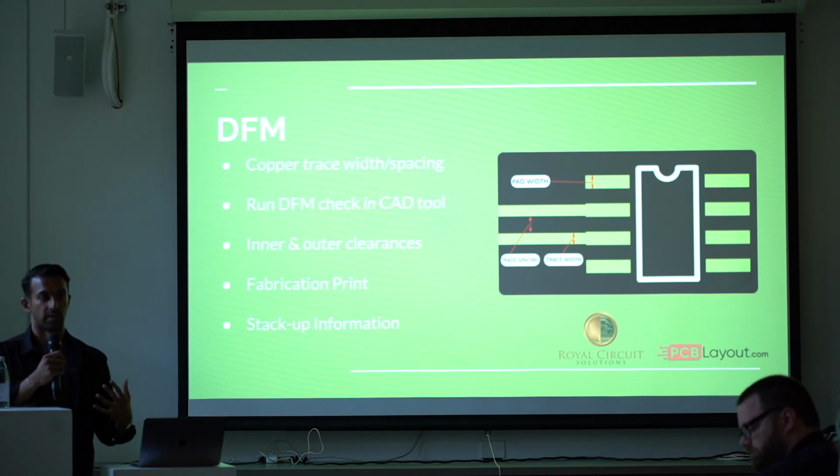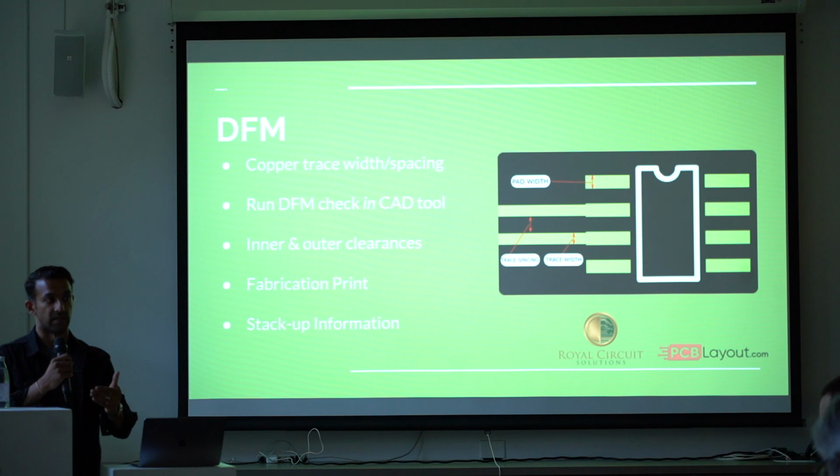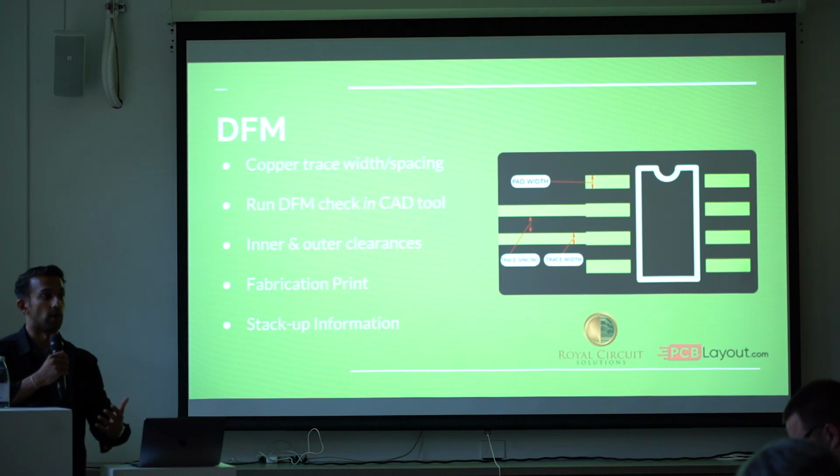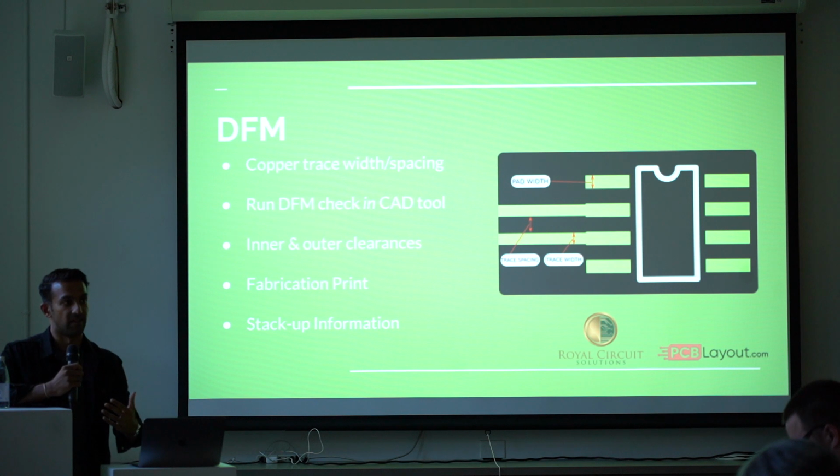So if you're running a particular design and you need a 50 ohm trace, for example, it's generally in your best interest to send us your requirements, and we would come up with a very specific stack up that would work for you and arguably be cheaper than what you can do or know on your own, because we know which materials to pick, how to give you the right stack up, and then tell you the different trace widths that you should be using to achieve that particular impedance.